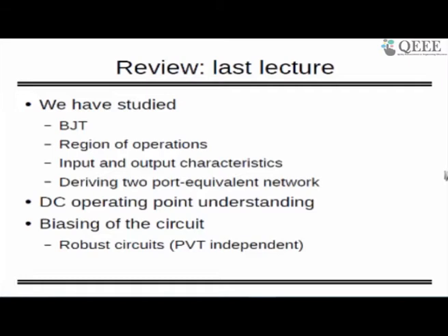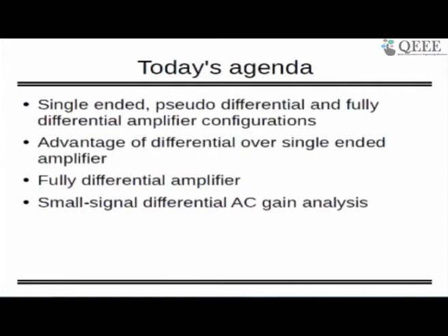I should keep one big capacitor, and the role of this big capacitor is blocking the DC which is coming from the top side, meaning VCC. So you should stop that DC current coming from the VCC side, and it should not be shared by my 50 ohm function generator, and that is how we kept a big capacitor. So this was one thing we learned.